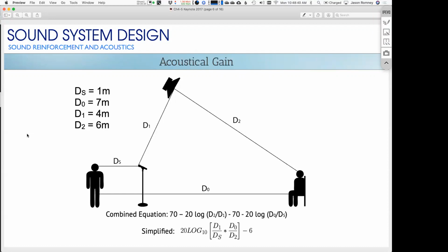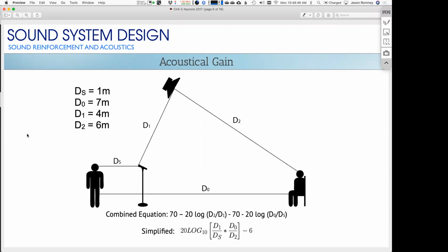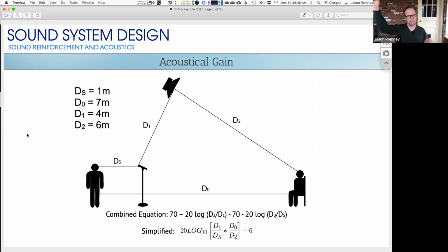The reason you move around is that you're changing the distance between the loudspeaker and the mic. Different frequencies are going to lock into that feedback loop. So he's trying to find the frequencies that feed back and kill them in an EQ. If you can kill that frequency that's trying to lock into a feedback loop, then it's basically getting muted while it's going through the sound system, so it doesn't feed back.